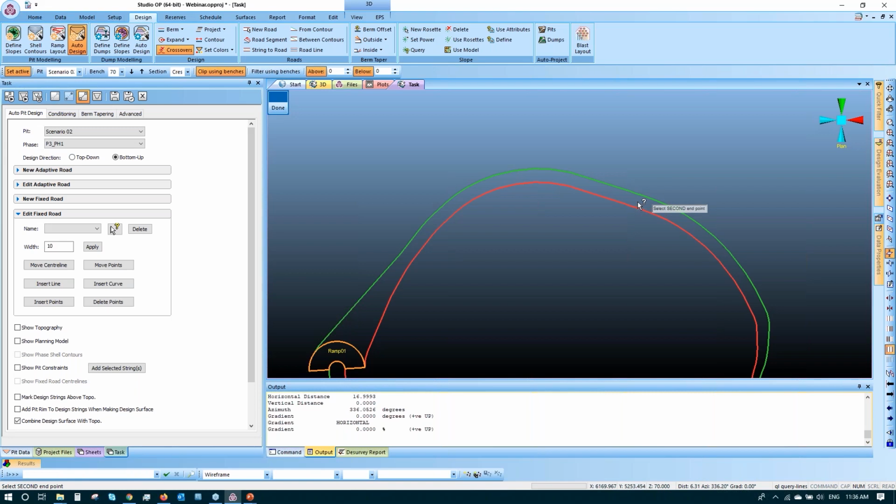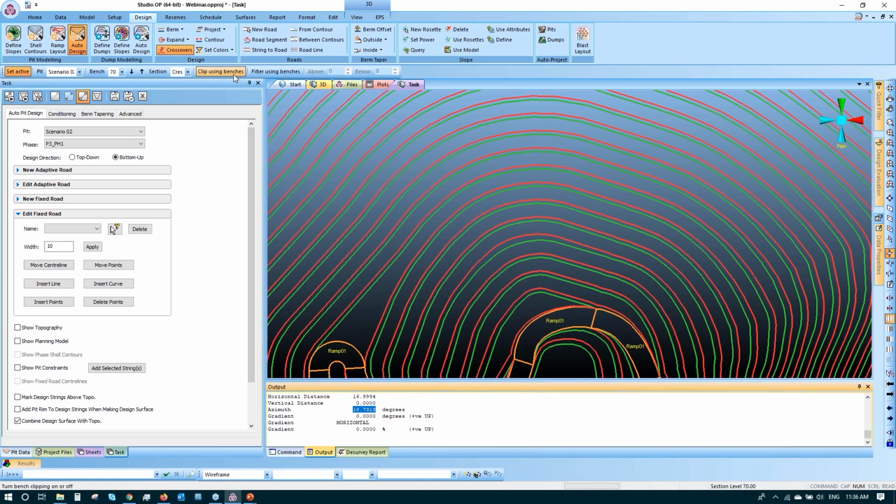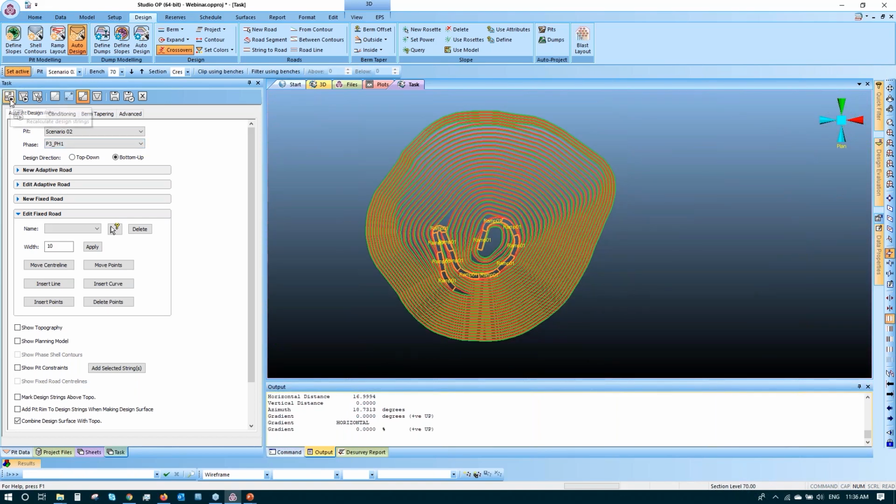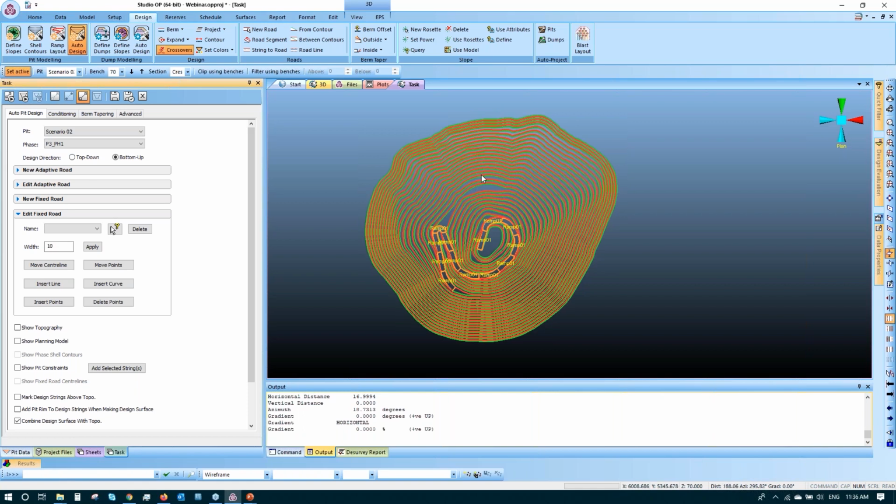Let's go to the side over here. So this azimuth here is 18. So it's already outside my range of azimuths. So I'm expecting that the software will do modifications more or less in this area around here. So if I unclip now, and now I will hit the recalculate button, and you can see that the modifications have been done to that area.